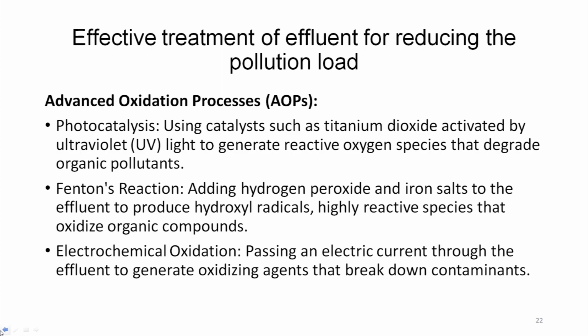Fenton's reaction, adding hydrogen peroxide and iron salt to the effluent to produce hydroxyl radicals, highly reactive species that oxidize organic compounds. Electrochemical oxidation, passing an electric current through the effluent to generate oxidizing agents that can break down the contaminants.